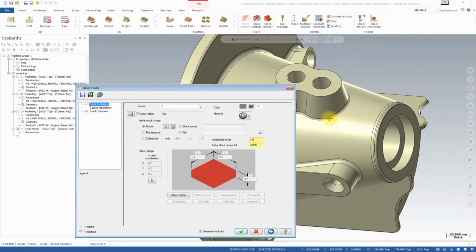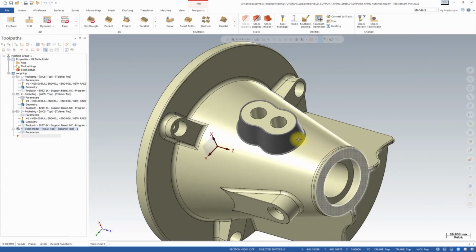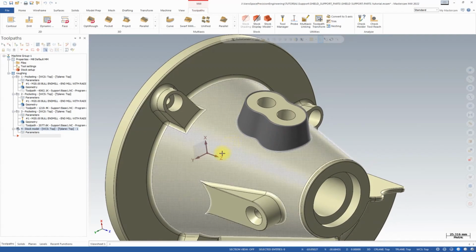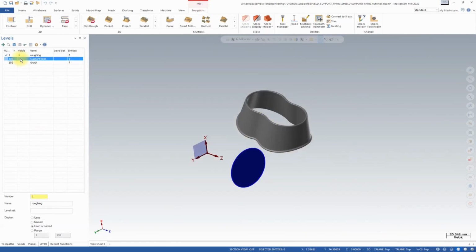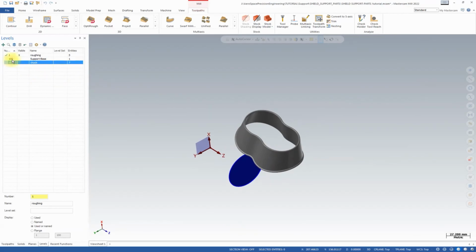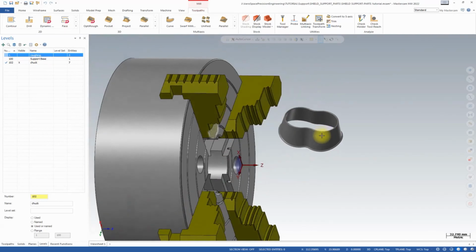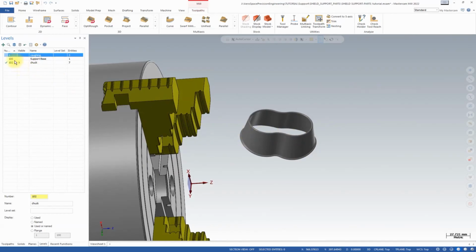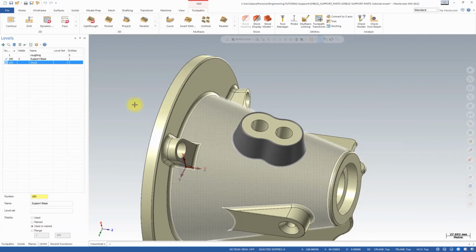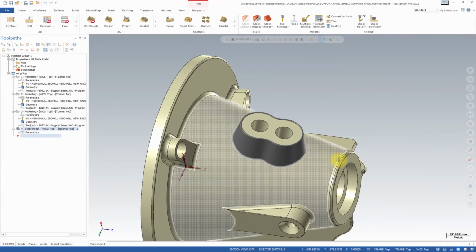And anything here that's set ready. The face of the fillet is selected, expand out 1 millimeter, click OK. Generate, see the result, the stock model will be generated. You can see the stock model is gray color, and we will see the 3D model stock will be generated. Talking about the stock model. Okay, this is my stock model result shown here.